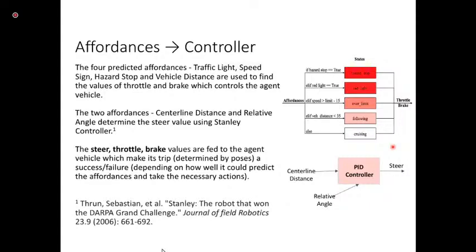And this lateral controller is again a PID controller. So it takes the center line distance and the relative angle, and it generates the steer angle which is required to achieve the center line distance and the relative angle.